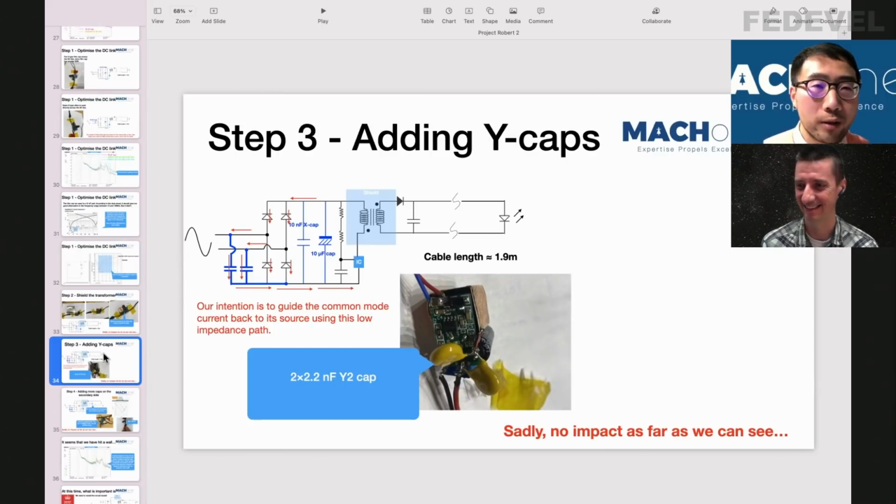One of the great tips from Keith Armstrong, in the interview he recently gave, is this: if you make step-by-step changes on a product, and the first step doesn't help, the second doesn't help, the third doesn't help, then as long as they're not making things worse, you shouldn't get rid of them. Leave them there. So now we're in step 3. Step 2 doesn't work, but I still have the shield.